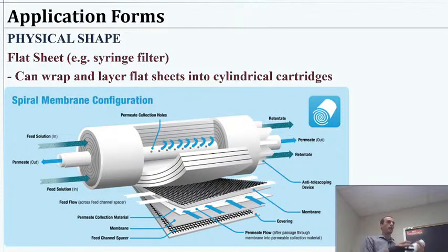And so it really allows us to make a much more compact, higher density situation for our membrane. So that's a great possibility, just winding the membranes. And that's an example of where the ceramic filters are going to have a disadvantage, because unless we perfectly crafted them into that form in the first place, which seems a hard task, the polymer membranes are going to have a big advantage here.